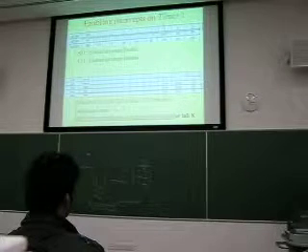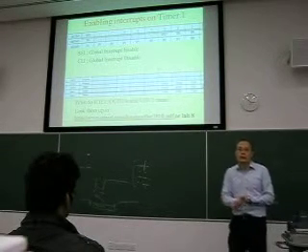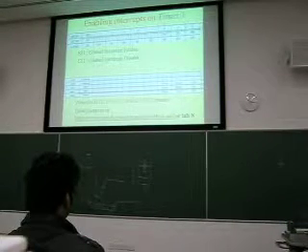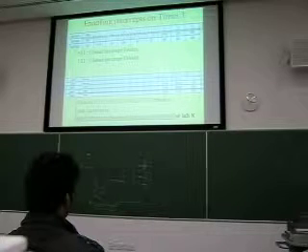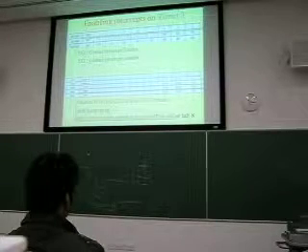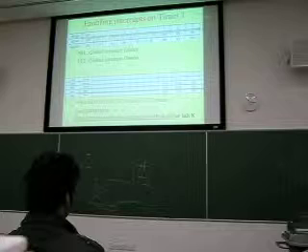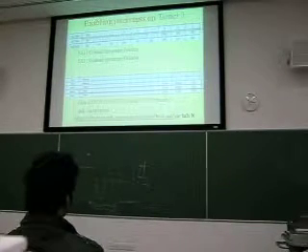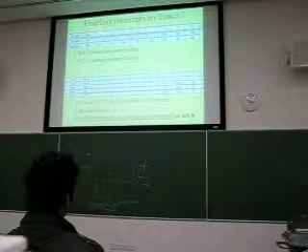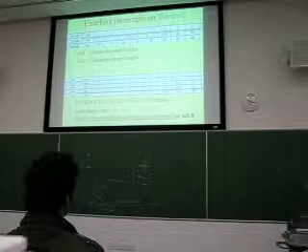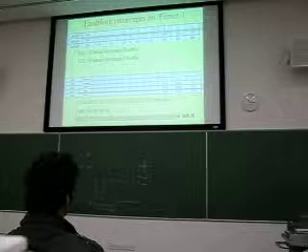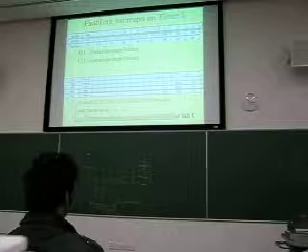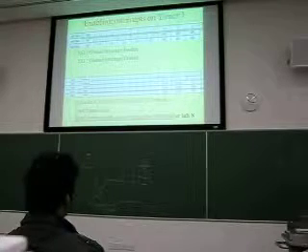So we've been talking about interrupts, and we mentioned previously about enabling global interrupts, which was in the status register. If you want to set that to 1, for example, this would be the syntax that you would be using. If you want to set that to 0, this is the AVR instruction that you will be using. Okay? But that's for all interrupts. That's for the global interrupts.